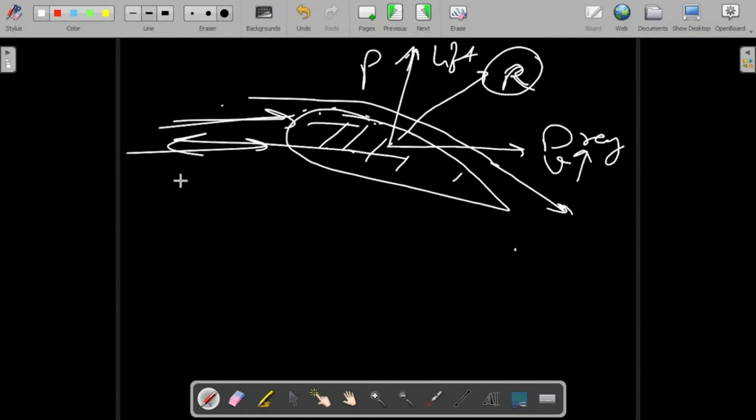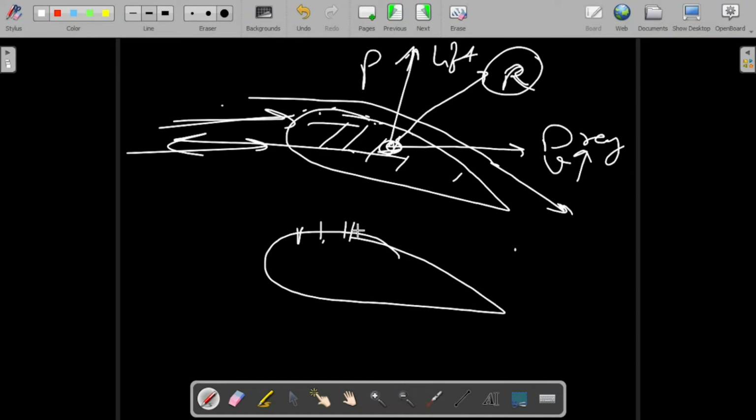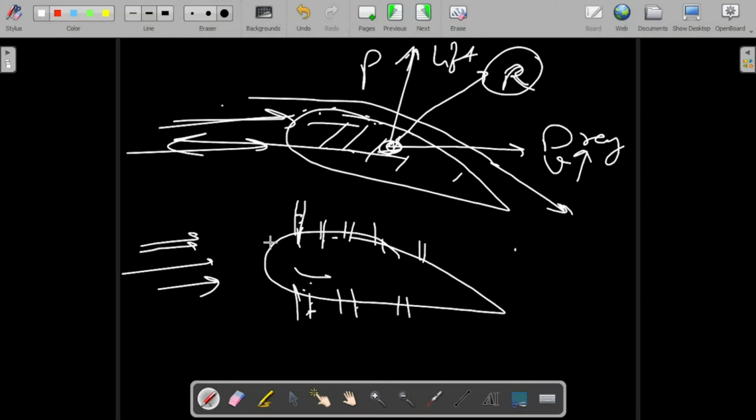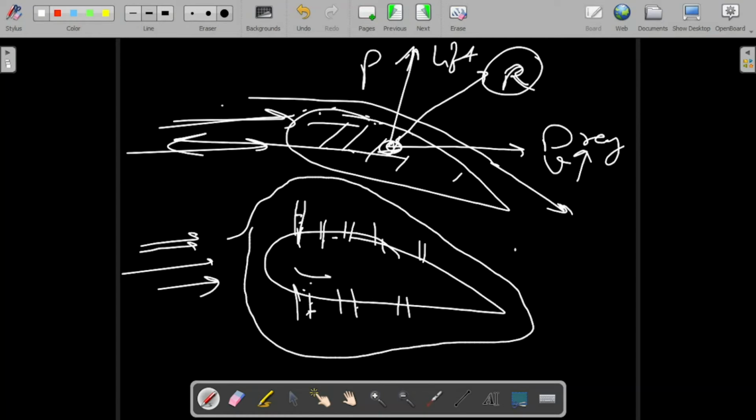So now we'll discuss the center of pressure, like from where we consider the point this pressure, this lift and drag is generated. There are many experiments which were undertaken, where they took this kind of section and fitted it with manometer tubes in all the sections, and then they measured, and when this section was kept in an airflow, they found that pressure at different points is at different levels. So when they drew the pressure distribution, they found, I'll just explain to you.